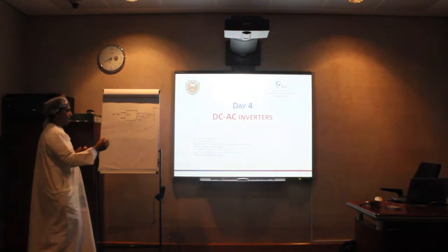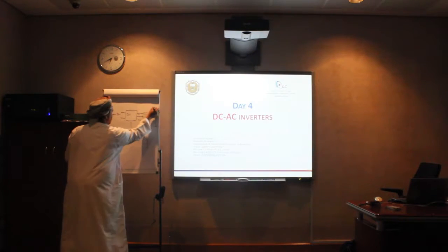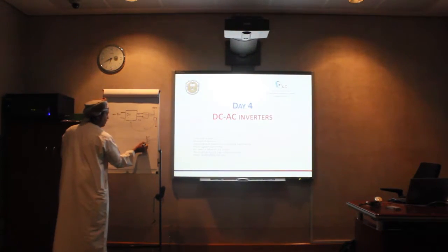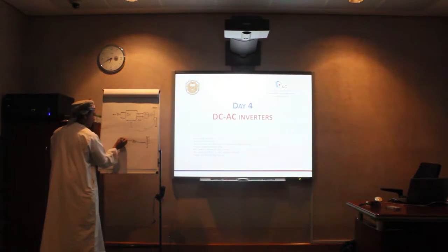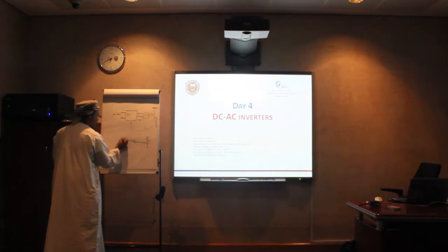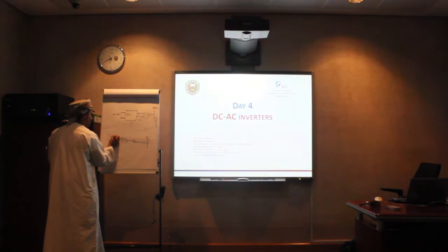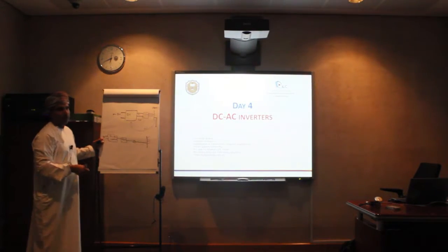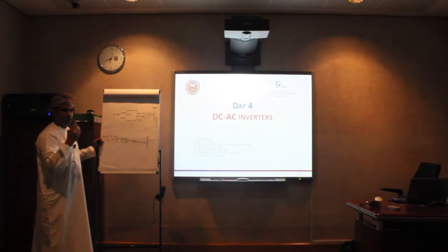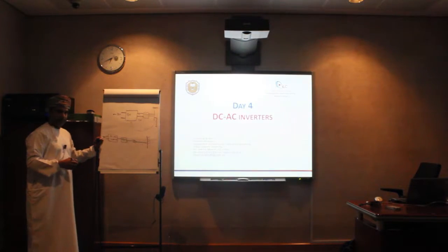connected system, definitely when you have a grid, if I assume this one is standalone, if it is connected to a grid, through a filter and then to the DC to AC inverter, and here the DC input could be from solar, it could be from wind, which is type 4 of wind turbines.